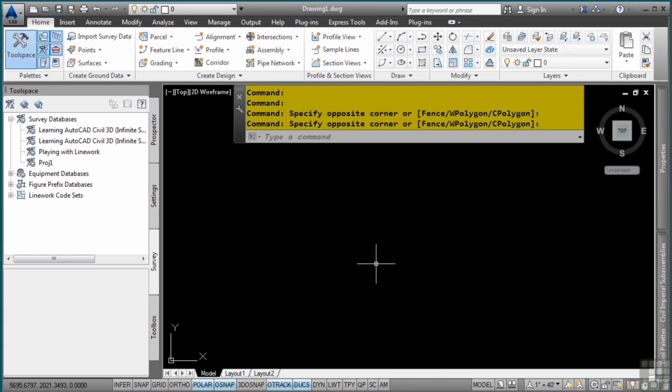When a survey point is inserted into a drawing from the survey database, a Civil 3D COGO point is created in the drawing. This point will have special attributes that indicate that it was created from a specific survey database. Survey points cannot have their locations and raw descriptions changed in the drawing because they are locked and set by the survey database.